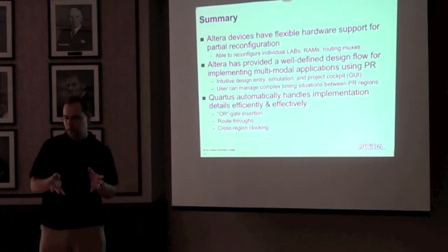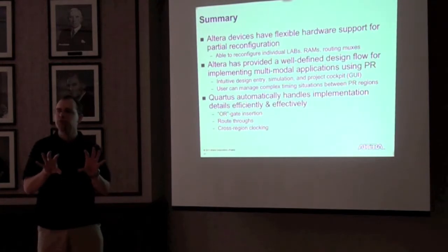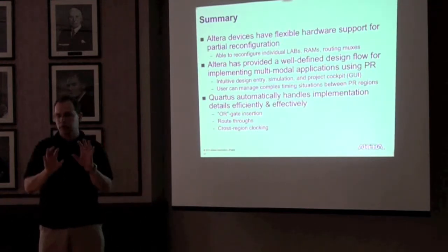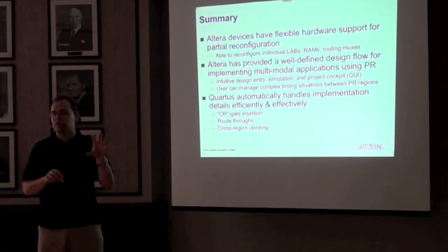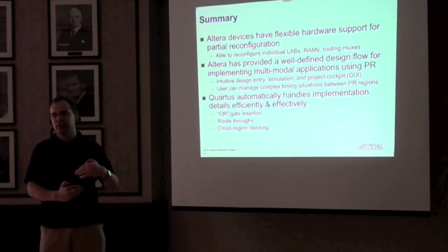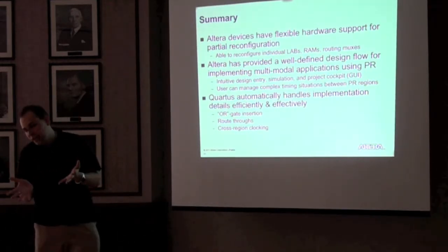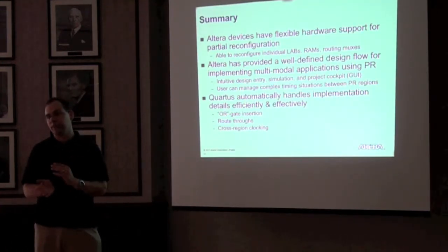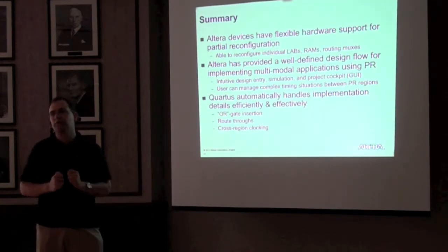So it's a good question. It was about the addition of a persona impacting clock region sharing. It's really more of a structural problem based on how the PR regions are defined. Without even talking about personas, if I know that the rectangles you have for a fixed logic lock region of 2 PR partitions cause an intersection of any given region, I know right at the base revision that I need to put those clocking resources in that base revision bit stream. So if you add a new PR region, almost guaranteed, your base is going to need to change. But if you add a new persona, that doesn't change the decision whether clock regions will have some new form of advanced sharing.